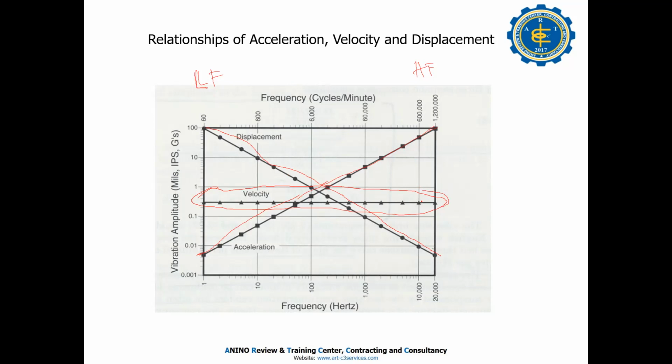But okay, on your side now, you use G's because your equipment to collect data is on anti-friction bearings, right? There's no displacement, no sleeve bearing. You're right, that's why you use this, because this is good in the high frequencies. Yes, in high frequency you can see the problem with the bearing fault.